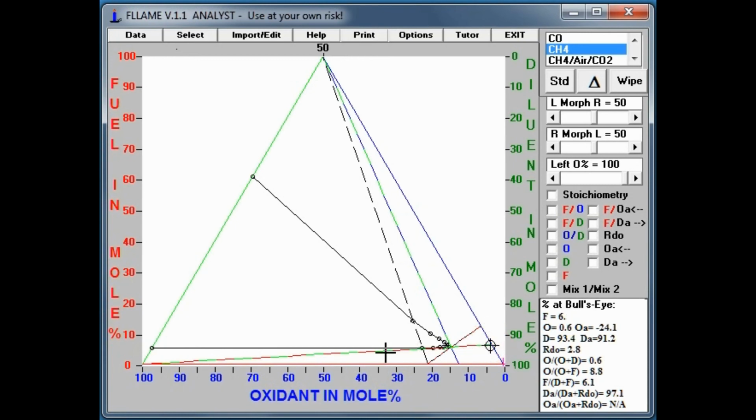And finally, I note that this point here is the 12.2% published min oxygen and nitrogen combustion limit. If you had a source or could blend 12.2% oxygen and nitrogen, you could purge the vessel to this point just off the nose of the fire region, and then elect any of 3 routes.